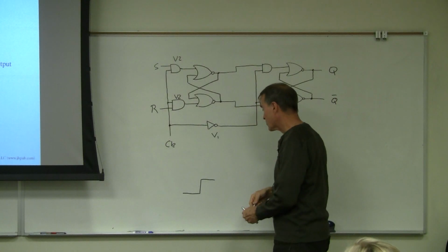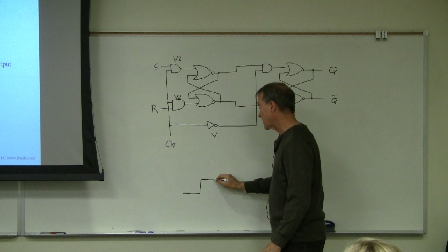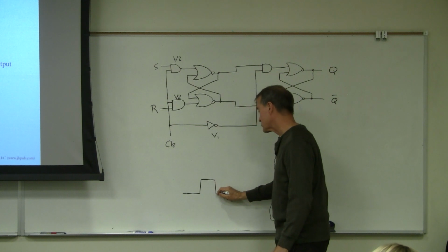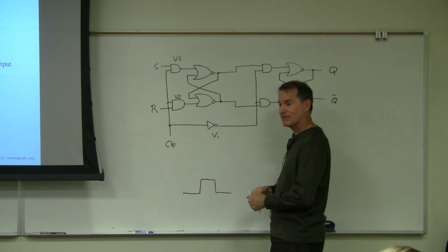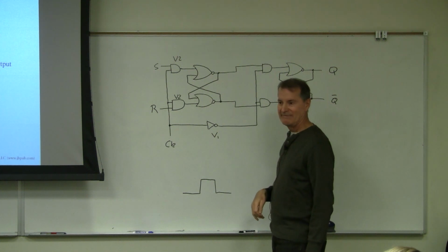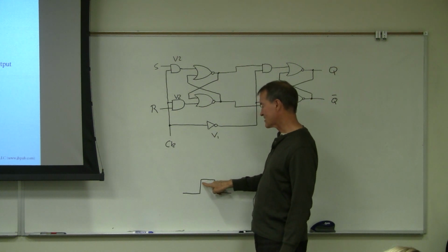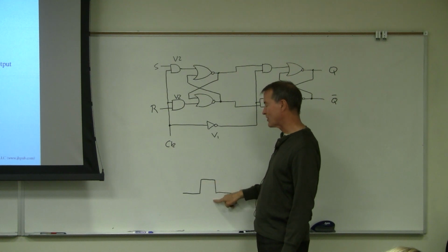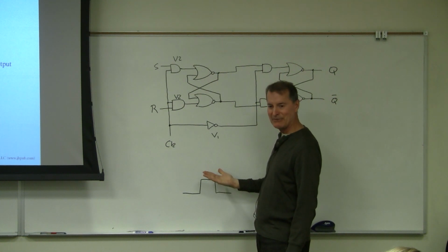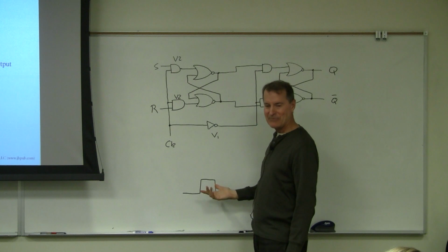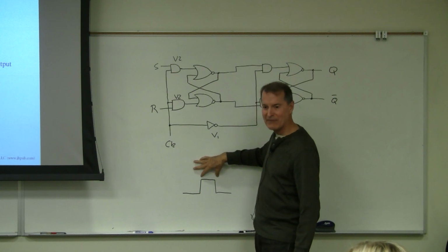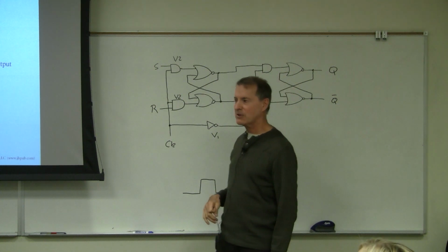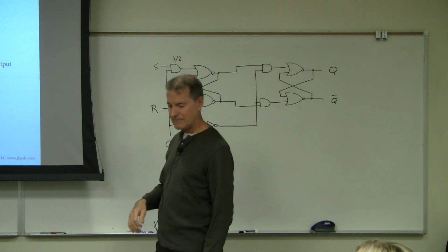And then, here's what would happen. When finally this clock pulse goes down, could you predict, if it does a billion transitions here, which state it would be in when it came down? No. You couldn't. If this was just a little bit longer, it might have made one more transition. You see what I mean? Is everybody with me on what the problem is?